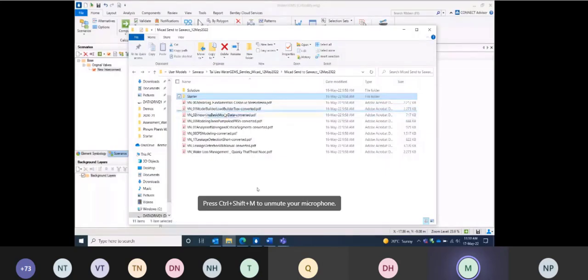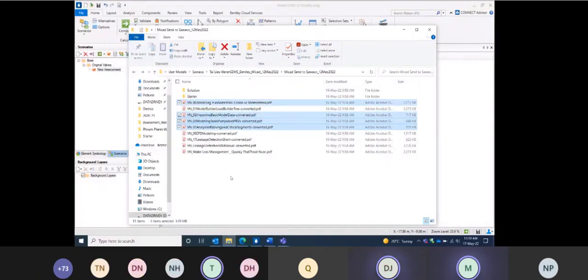Okay. So welcome back, everyone. Thanks for joining again. So yesterday we covered 4 workshops. Today we've got 3 workshops, but the 3 today are a bit more in-depth than some of the ones yesterday. So yesterday we started with the very simple importing of just the pipes and the junctions, and then we went and fixed it up by morphing some elements and then putting some settings into those elements, so a pump curve and some PRV settings, and of course tank elevations, reservoir elevation.